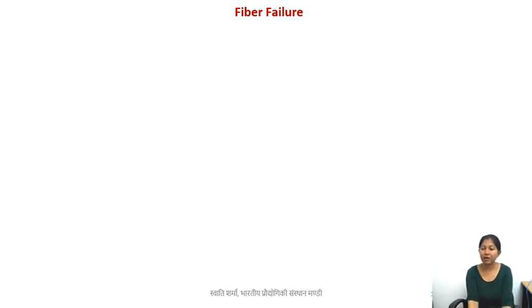So mainly the material failures. Because the construction is from fiber reinforced plastics, whether they are glass fibers or carbon fibers, there may be some issues of the compatibility between the fiber and the matrix material. That is one major problem, and that is why a lot of fiber related failures take place. Then there are some other issues, for example, because of the tension in the blades, the fibers can break, or because of the compression, the fibers can deform, and so on.